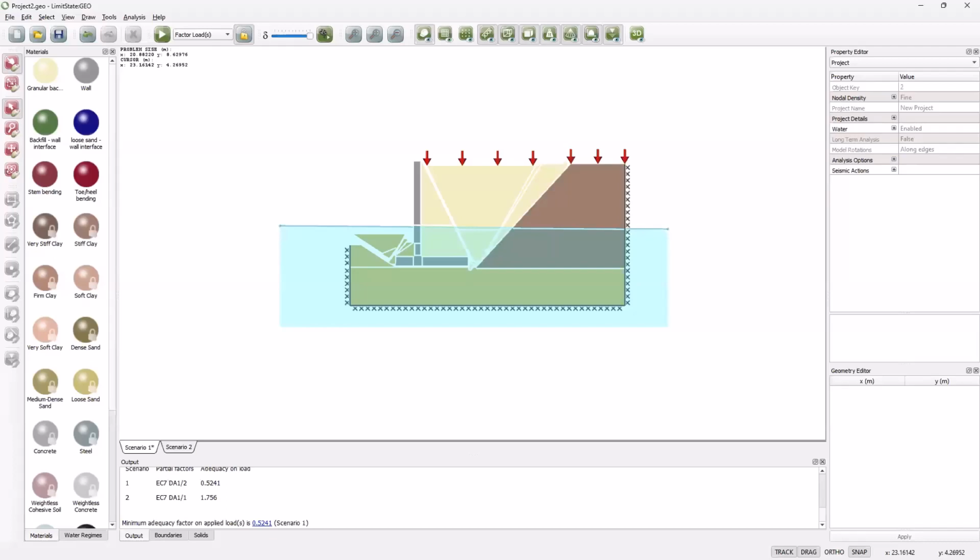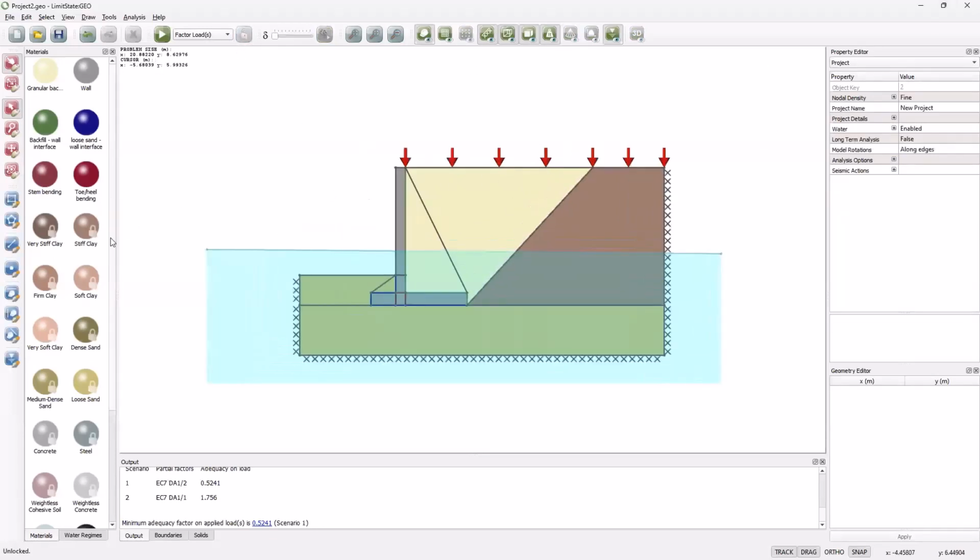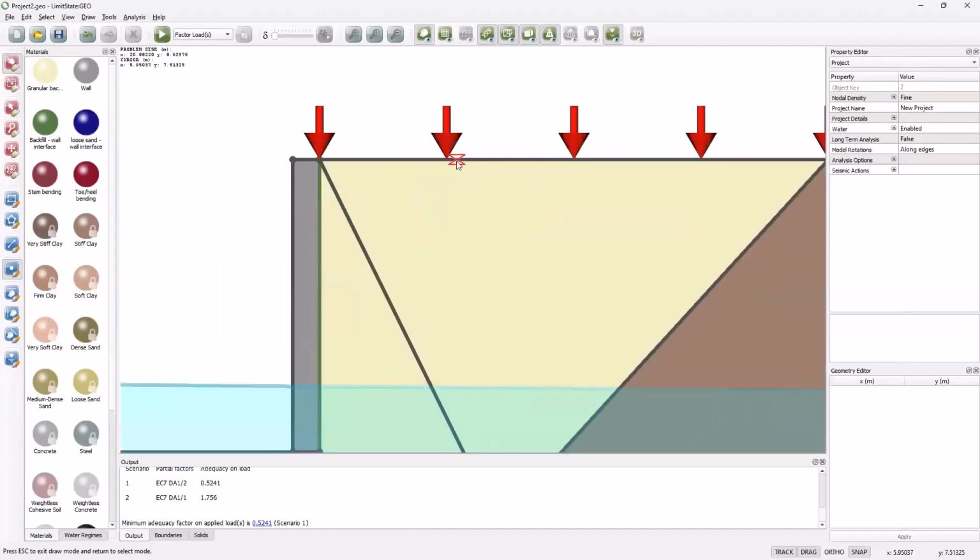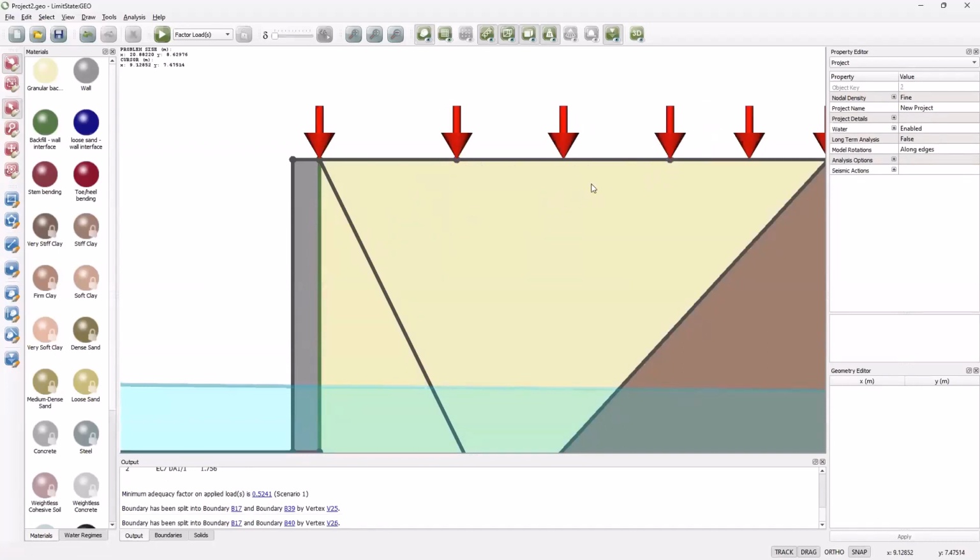Can we add exclusion zones for loads? Yes, so I can quickly show that one. If I want to have the load over a smaller area, I can use this vertex tool here on the left. I can add vertices to, failing to get that to click. Let me try again. Zoom in a bit more. Yeah, one there, and say another one there.